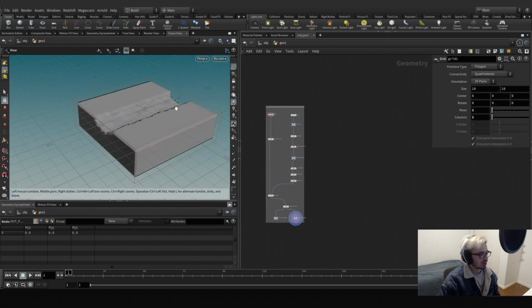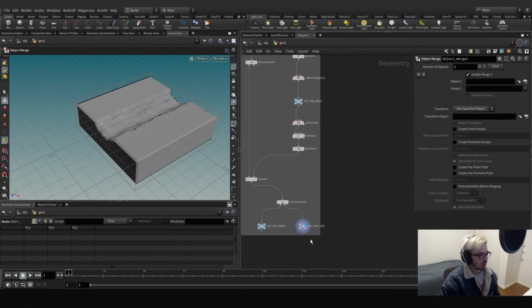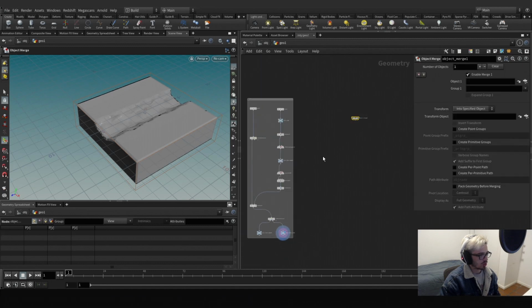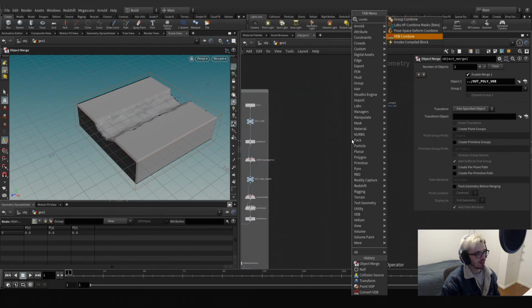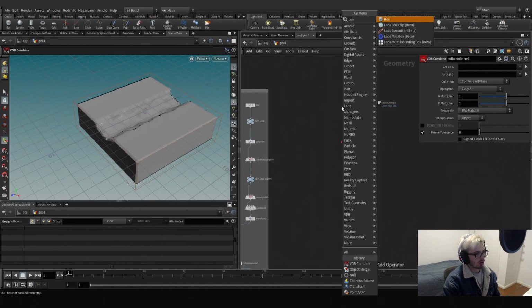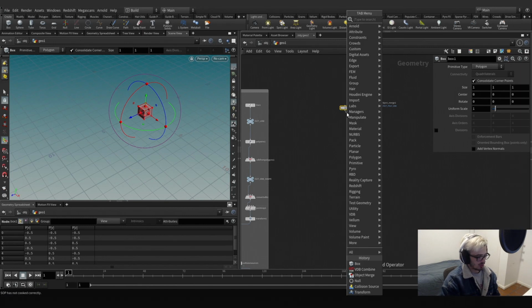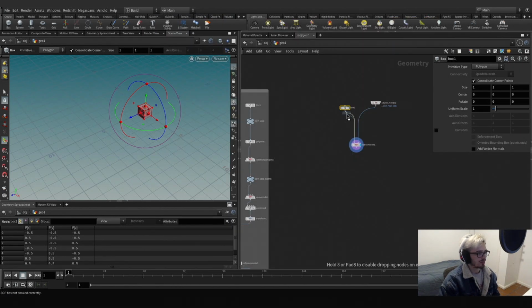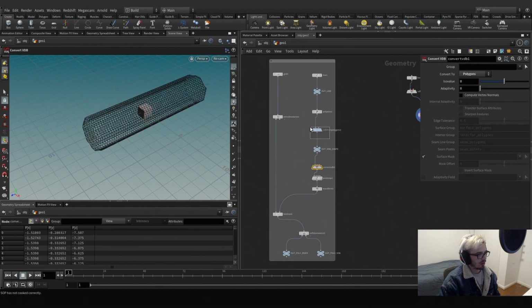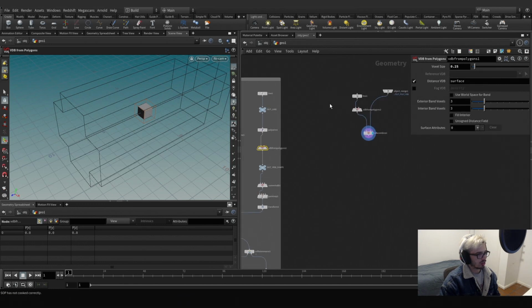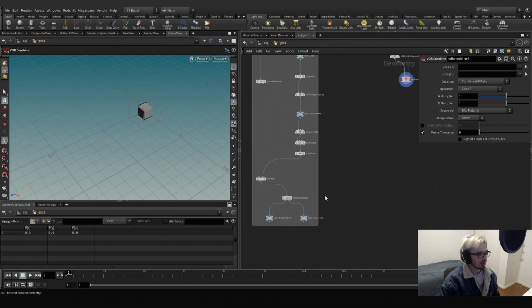So now we've got to make our initial source right here. Let's also merge our poly VDB because we're going to use it to have a combination. It will combine VDB. So let's also make a box. This box will determine our initial shape. Let's do a VDB from polygons. This will have our voxel size, so it will remain constant everywhere. And we will combine all the things.